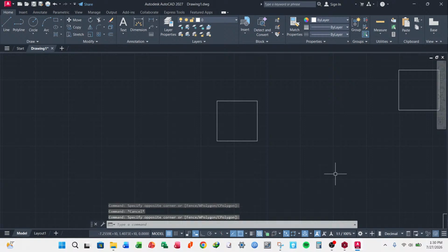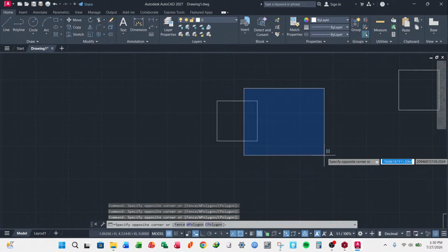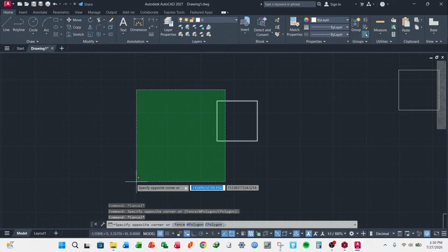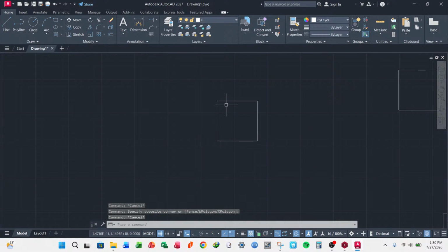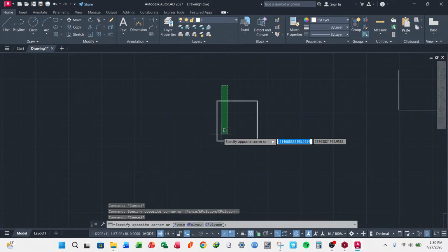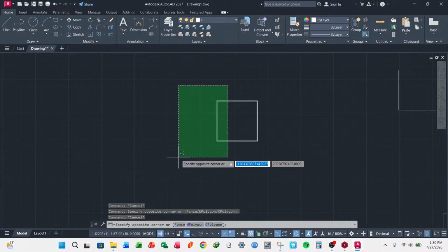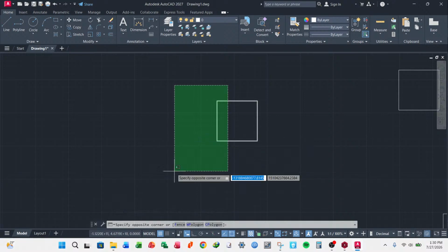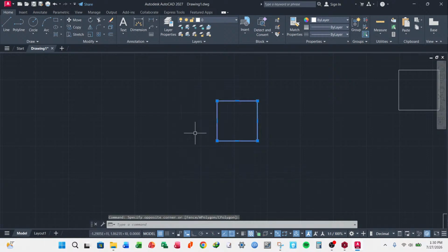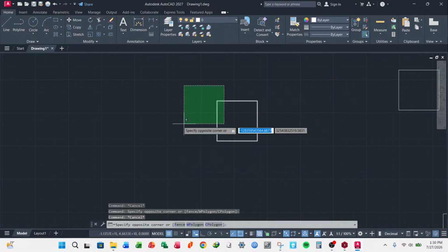There's left to right, where the selection window is blue in color, then right to left you have a green selection box. A green box, right to left, is a way of highlighting an object by simply touching on it.